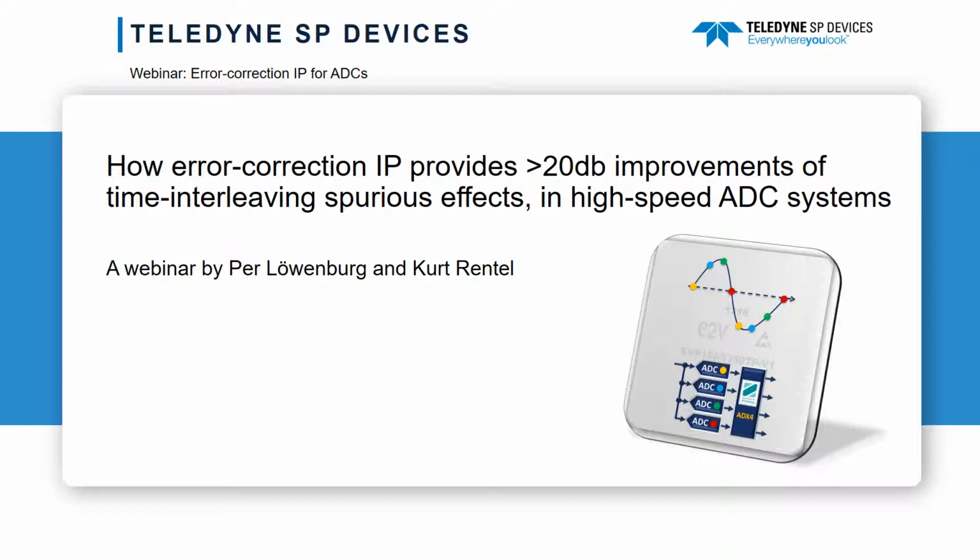In this webinar, we will highlight the possibilities of digital error correction in gigasamples per second analog to digital converters. We will share some insights in so-called time-interleaved ADCs and illustrate the effect of mismatch and mismatch error correction. We will further demonstrate mismatch error correction using the commercially available Teledyne SP Devices IP.CORE ADX.